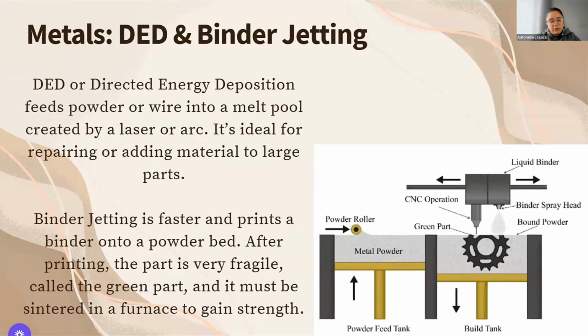Another technology, very interesting nowadays, is DED and binder jetting. DED is directed energy deposition that feeds powder or wire into a melt pool created by a laser or arc. It's like soldering. It's ideal for repairing or adding material to large parts. So it's a combining technology.